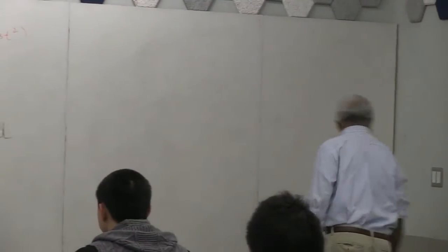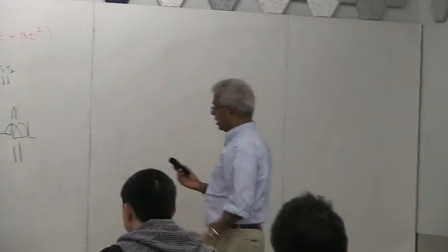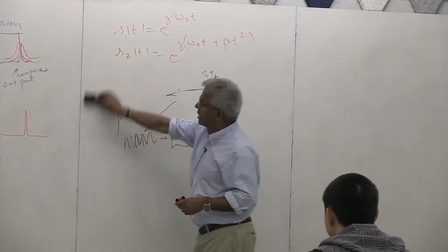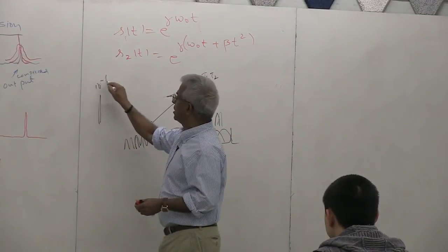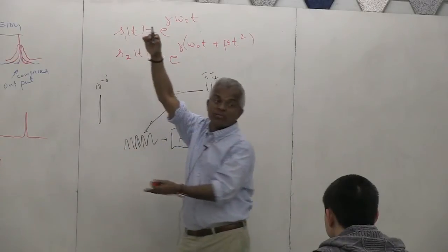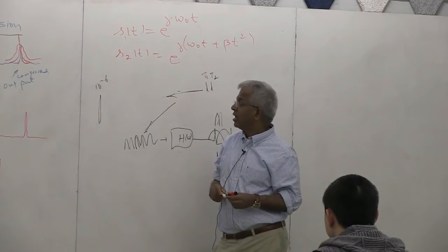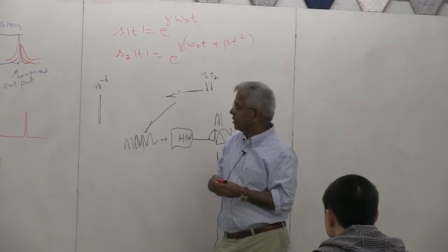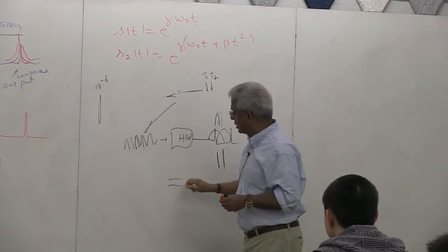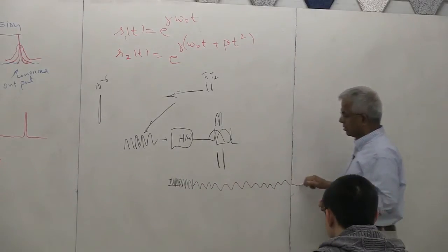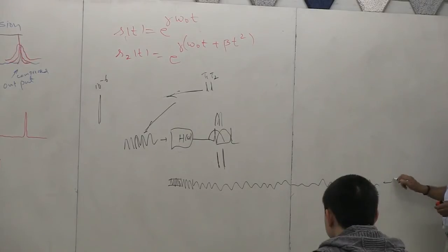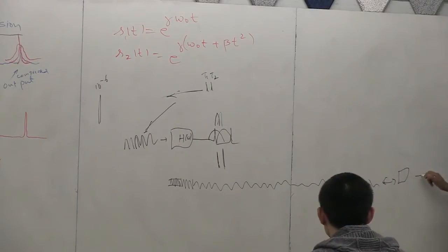It's very important. But you may say, why don't you transmit a very narrow pulse, a very short pulse? That's impractical because if you want to transmit a pulse of only duration 10^-6, its amplitude will have to be very high. So what generally is feasible is to transmit a very low amplitude pulse for a long time. But then if you can pass it through a filter and make it look like this, that's what we mean by pulse compression.